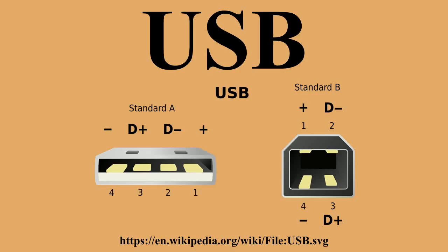A USB device could have up to 32 endpoints, though it's rare to have so many. An endpoint is defined and numbered by the device during initialization and so is relatively permanent, whereas a pipe may be opened and closed. There are 2 types of pipe: stream and message. A message pipe is bidirectional and is used for control transfers. Message pipes are typically used for short, simple commands to the device, and a status response, used, for example, by the bus control pipe number 0.